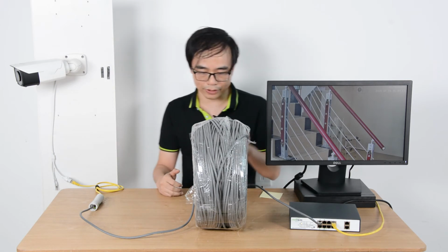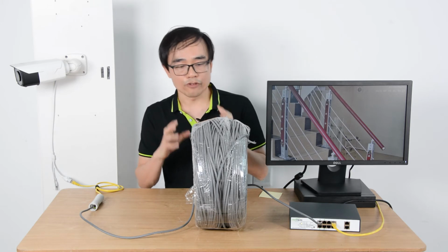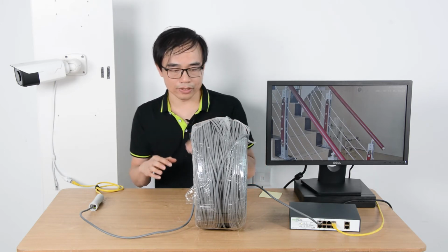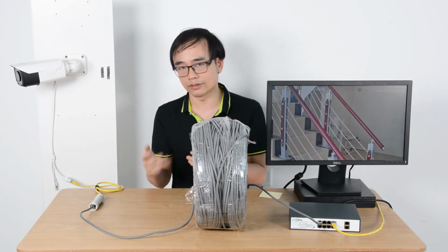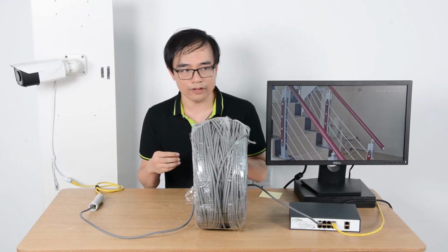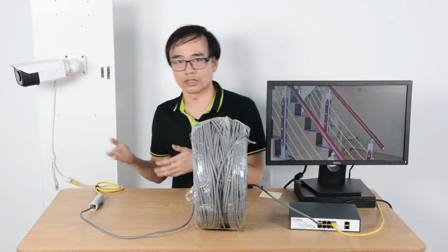The reason is that this 800 meter PoE switch uses 4 pairs to transmit the power. In PoE and PoE Plus, only half of the twisted pairs are used to send power. That's the reason. The second thing is it's using 54 volts. It improves the voltage, so as to reduce the voltage drop.